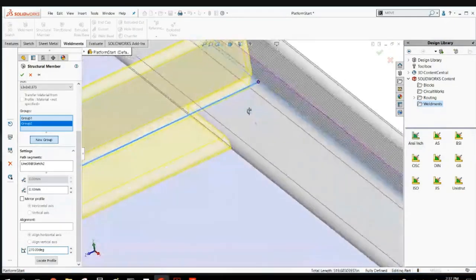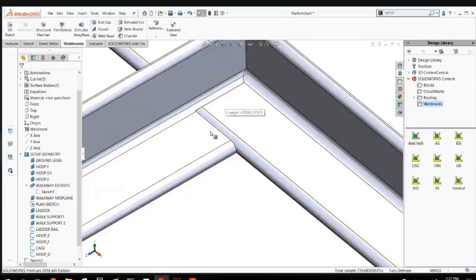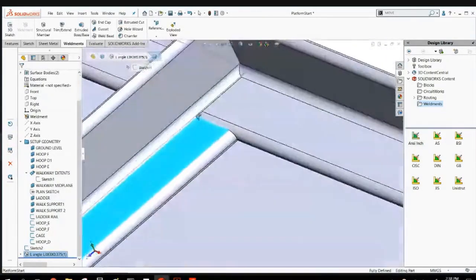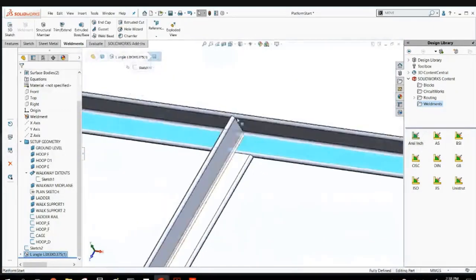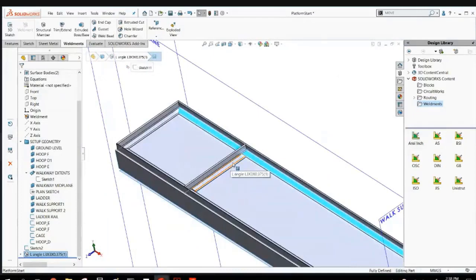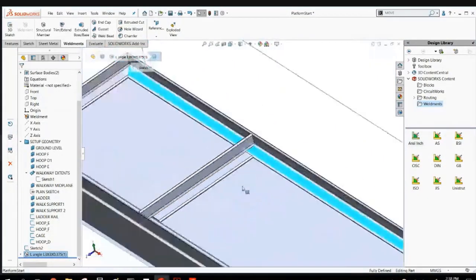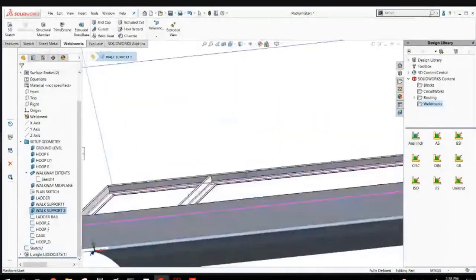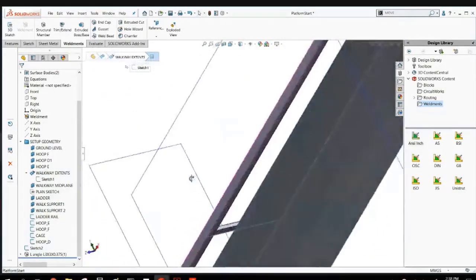Notice that it will try to cope these to one another where it's breaking this off. It's just not very good at it. It doesn't know enough to take this fillet out of there. So a lot of times, if you are trying to get it exactly like you want the thing cut, you would need to open a sketch and cut that little area off of there. It's pretty easy to do. Let me hide this surface.